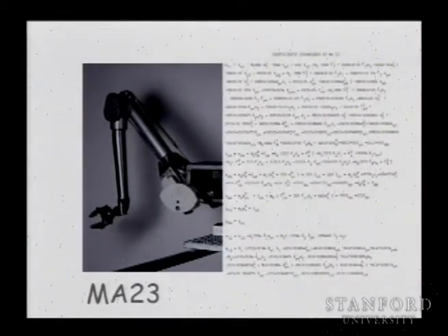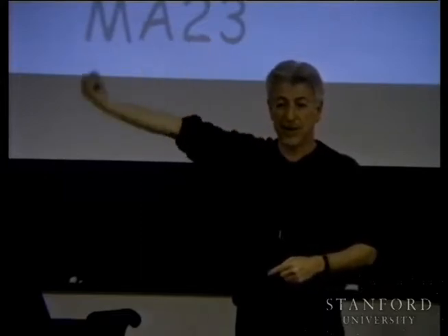So you see on the right here, this is the robot, and here you have some of the descriptions. You cannot see anything probably, but you have all the descriptions of, for instance, the inertia viewed from the first joint when you move. So this inertia is changing as you move. Imagine I'm considering the inertia about this axis. If I'm deploying the whole arm, the inertia will increase. If I'm putting the arm like this, I will have smaller inertia about this axis. Bigger inertia, smaller inertia.